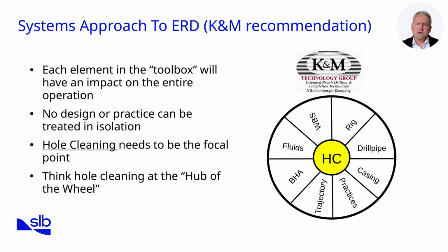The K&M methodology emphasizes that each component in the toolbox has a knock-on effect. For example, choosing a low-friction BHA design may reduce torque but can compromise steerability. Similarly, a mud program optimized for rheology may affect signal strength of LWD tools. The key is balancing these trade-offs. By looking at ERD through a systems lens, we maximize efficiency, reduce risks, and increase the chances of delivering the well successfully. With that principle established, let's move on to a summary of the technical issues we face most frequently in ERD wells.